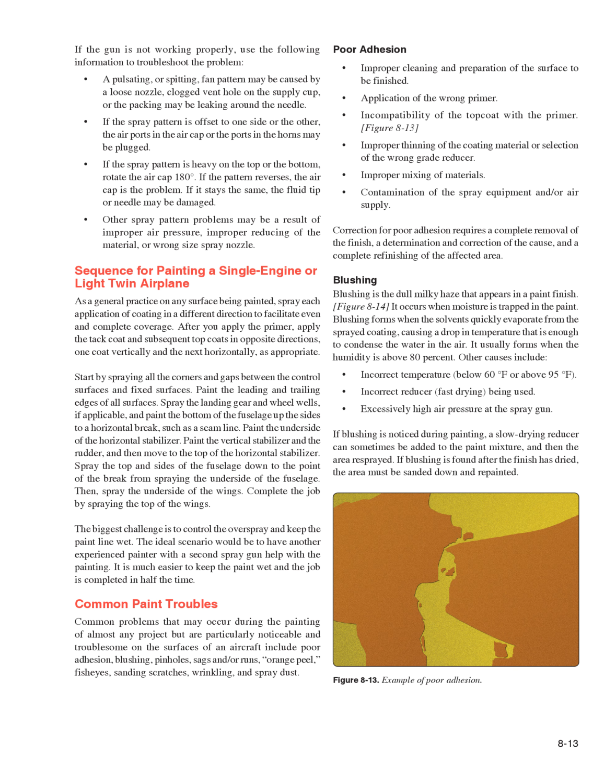If the spray pattern is heavy on the top or the bottom, rotate the air cap 180 degrees. If the pattern reverses, the air cap is the problem. If it stays the same, the fluid tip or needle may be damaged. Other spray pattern problems may be a result of improper air pressure, improper reducing of the material, or wrong size spray nozzle.